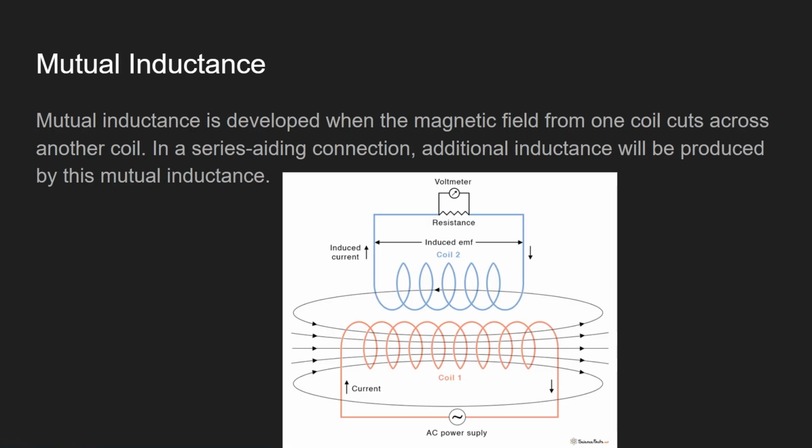And mutual inductance is more widely used. We have a power supply here, and a coil, and they have an alternating B field, right? The magnetic field flux will cut through the second coil, so it can transmit the energy to the second coil. The second coil will receive the energy and drive this circuit. This is called mutual inductance.